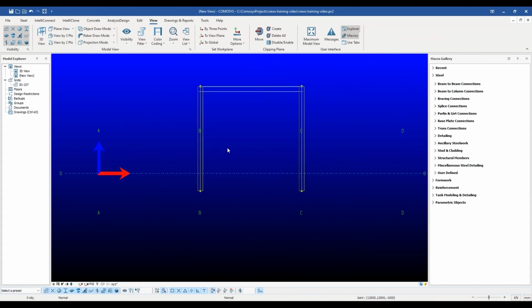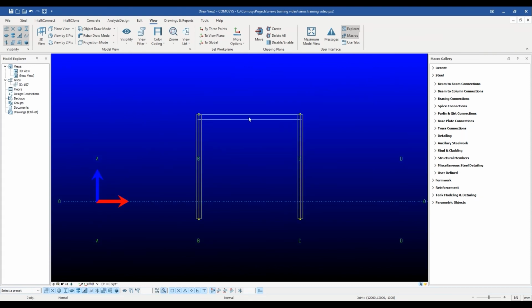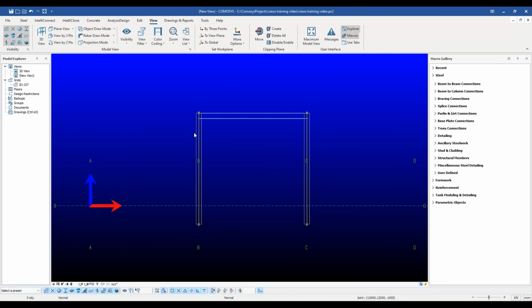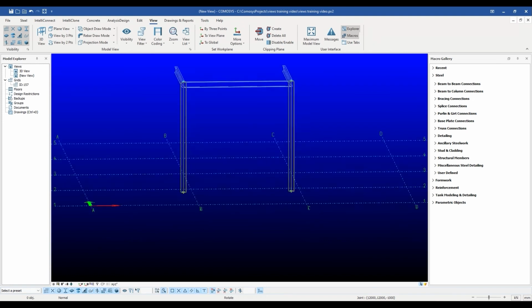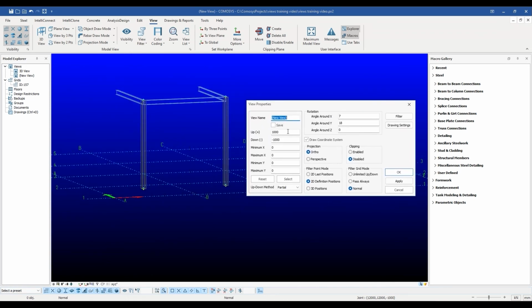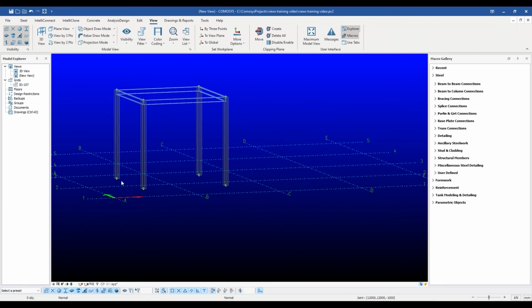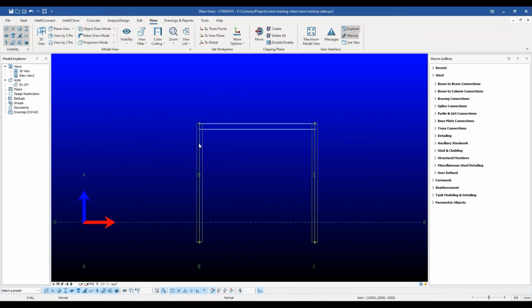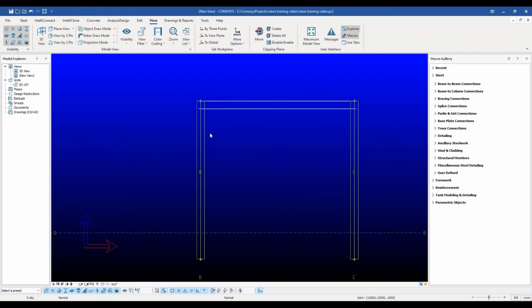This command is very useful for taking sections from plan views. However, it is quite general and you can basically create a sectional view in 3D space as well. Let me adjust up and down limits as we already discussed to get a full view of this model in this newly created view. The only constraint is that the 2 points chosen need to be in the plane of the view in which they are being chosen.